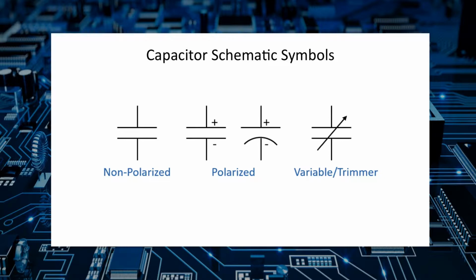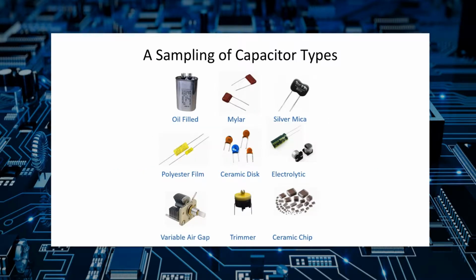Unlike resistors, certain types of capacitors are polarized. Electrolytic and tantalum, for example. Polarized capacitors are not tolerant of reverse voltage and will either break down or explode when reverse biased. You'll see that at the end of this segment. Everybody loves that part. Polarized capacitors have their leads clearly marked as to which is the positive and which is the negative.